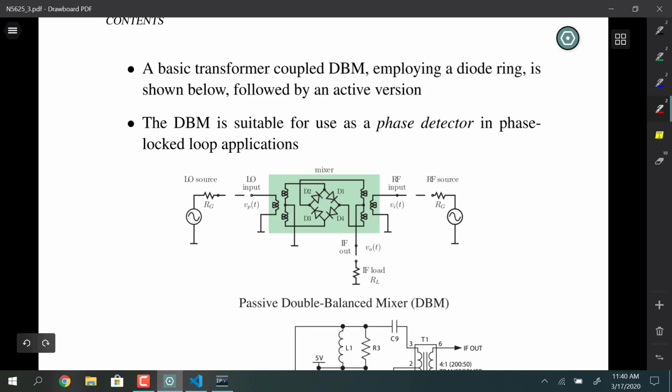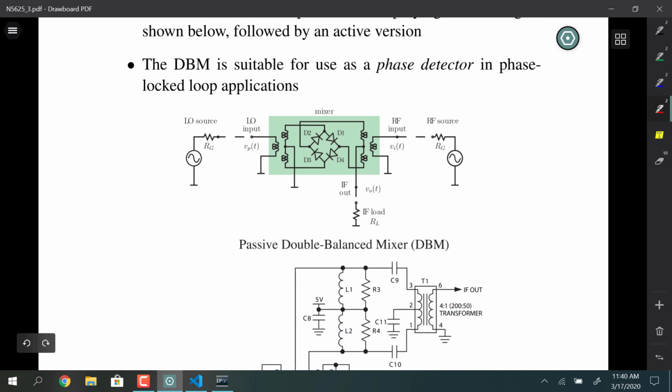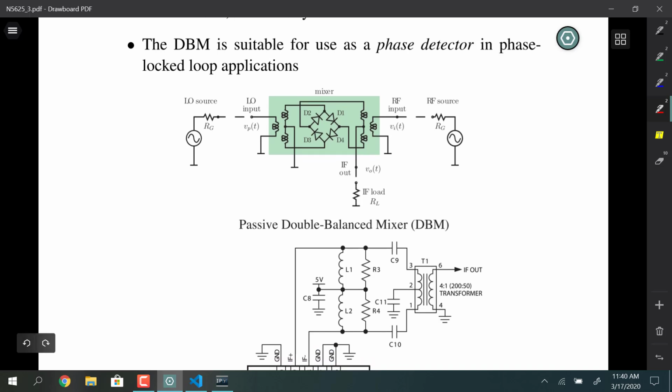So this is another popular mixer in passive electronics, using the diode ring with diodes on a substrate that are all matched. They're generally Schottky barrier diodes because they have a very low turn-on voltage and they switch fast. And then you have transformers to go from what would be called an unbalanced single-ended signal form to a balanced form. So the opposite side of the transformer has a center tap to ground, and that arrangement drives the diodes.